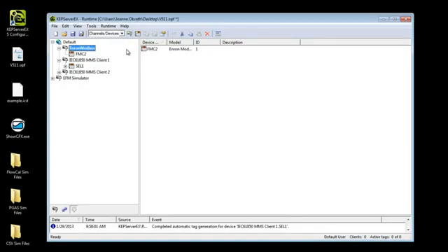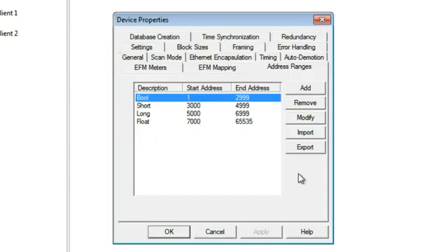The original Enron Modbus specification defines set address ranges for each data type, but with our 5.11 driver, this is now completely configurable by users. Start and end addresses for data type ranges may be managed in the Address Ranges tab in the Device Properties window. The native data types a user may specify include Boolean, short, long, and float.